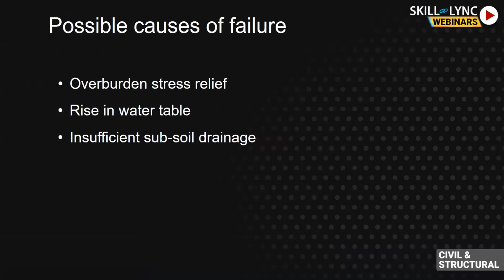Here in this case, the ground was cut in a hill of 15 to 20 meters depth, as I previously mentioned, causing this unloading situation. Over time, the ground adjusts to this loss of overburden and strength decreases, especially for cut slopes.